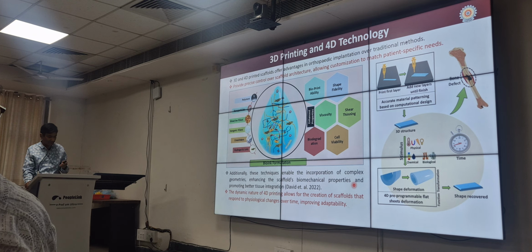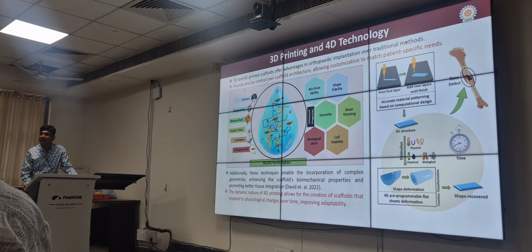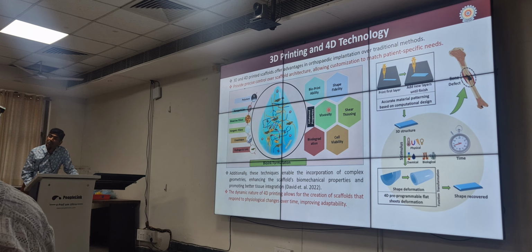So here, if we talk about the varieties of materials that could be used to make the ink for 3D printing, right? In these bio-ink formulations, all these are the components. But we have to see some important properties, like bioprintability, and this is not a single word. Behind it, so many factors are there. For bioprinting, we have to see how much viscosity is required. It may differ from model to model. The model that you have purchased may require a different viscosity from what I am using.